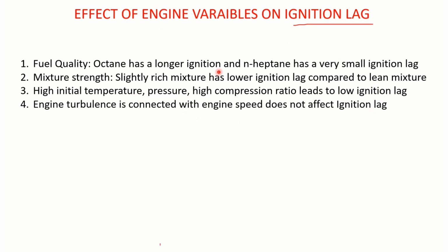Later you will understand the importance of ignition lag. It is necessary in a petrol engine. We should have a reasonable ignition lag, otherwise it leads to abnormal combustion, which I'll be discussing a little later.